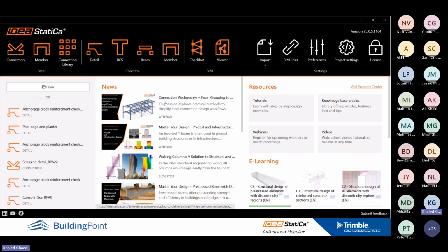And in terms of the crack width, which is under serviceability, you can click on the crack width, and then here we specified that the limit crack width is 0.3 mm. So you can again look at the location of the crack, if you remember. By doing the topology optimization, we are actually in the tension zone at that location. So you can see the graph just by clicking on each location. And you can go to the utilization ratio of the crack width as well, the real crack width value versus the limit one. And also you can look at the deformed shape, let's say linear deformed shape of the section under applied load, and also under short term, if you remember.